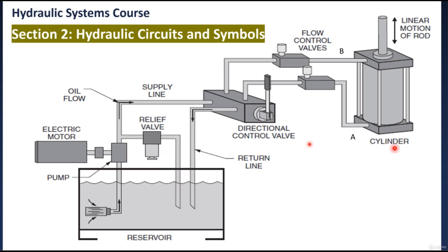The movement of this piston is normally controlled by changing liquid from port A to port B. The cylinder movement is controlled by using control valves, which direct the fluid flow. The fluid pressure line is connected to port A in order to have the piston raised up, or connected to port B to have the piston lowered down. The valve can also stop the fluid in any of the ports.